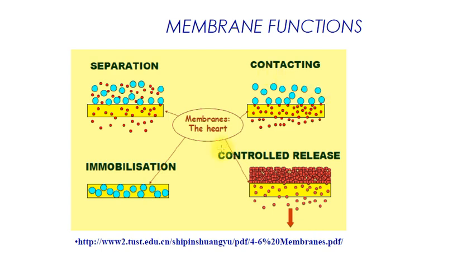Say you have a liquid and a gas, and you want to increase the contact between them in a reaction. It is a heterogeneous reaction where you want to increase the surface area of contact. You can use the membrane as a separator between the liquid and the gas, and the membrane will provide a very large contact area. Otherwise, only bubbles of gas would form in the liquid, and that would give a very small surface area.